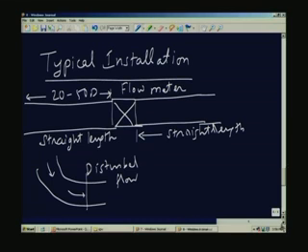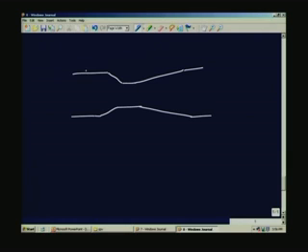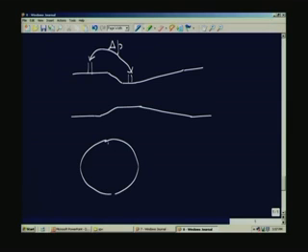The other point I would like to talk about is what is done normally if you take the Venturi, for example. So, this is typically the Venturi. You are going to measure the pressure difference between these 2 points. This is delta P, what I am going to measure. So, normally what is done is, you have several taps on the periphery. So, you have the pipe here, I have taps. This is the pipe thickness, I have several taps.